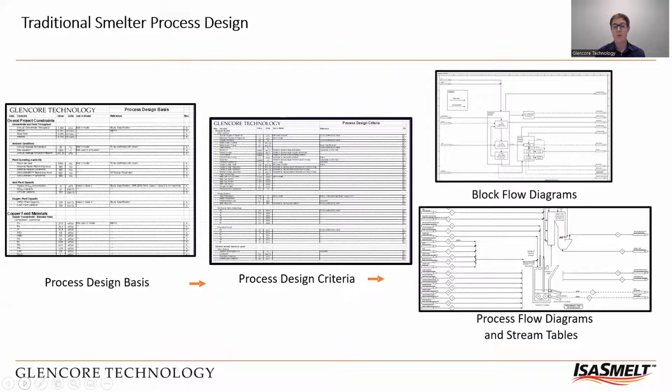From this, they take the process design basis, process design criteria, and do some basic calculations and produce block flow diagrams and process flow diagrams and stream tables as well. And so this particular approach is based on benchmarking and existing operations. The calculations are not necessarily complex, and they can be fairly simple.